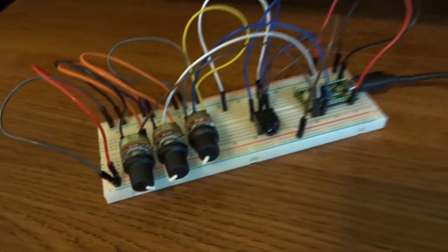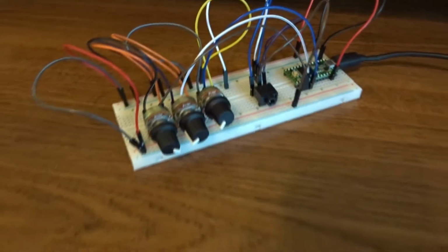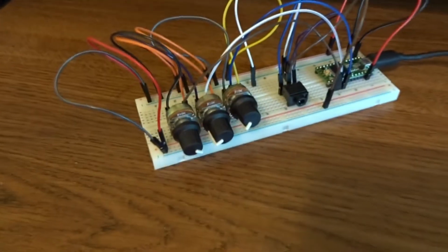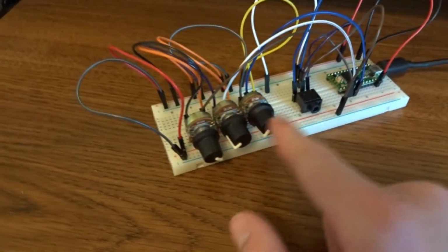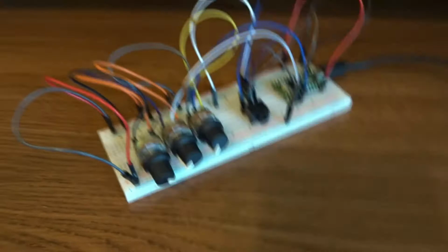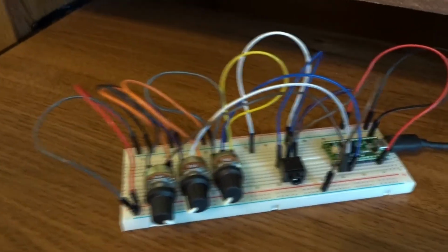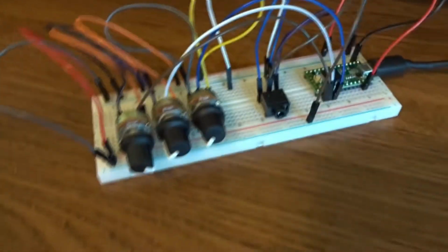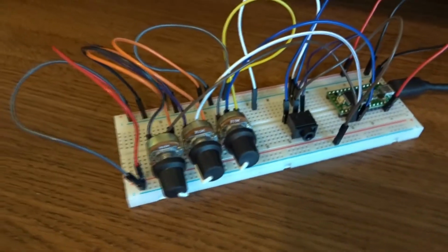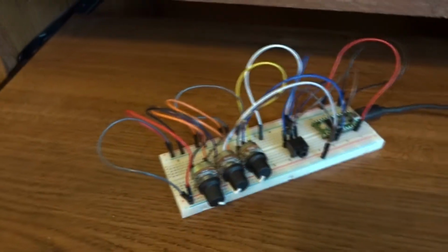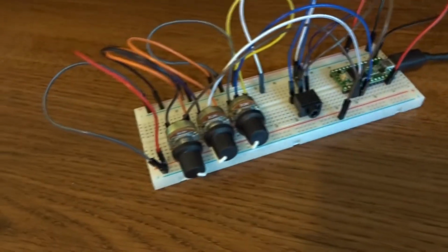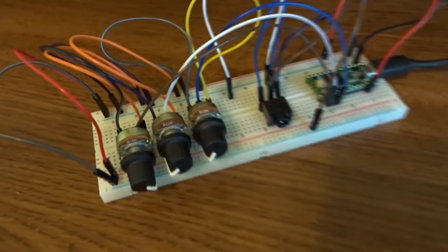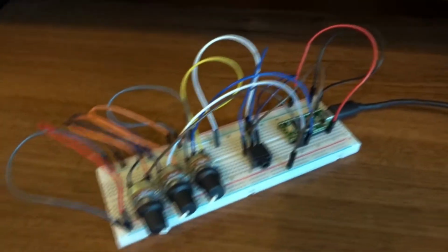So this is what I've been working on, and it's basically just a single oscillator with three controls. The first control is attack, the second one is hold, and the last one is release. My goal was to make an oscillator like an envelope, like an AHR, attack, hold, release envelope, except it loops really fast so it makes a sound. That allows me to get really interesting wave shapes and also the traditional sawtooth, triangle and square with variable pulse width. So that gives me a lot of stuff.